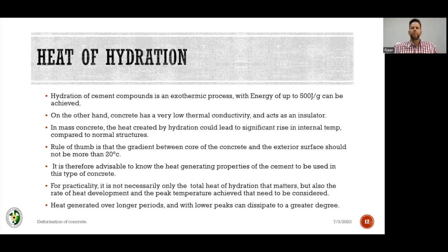consultant and the client. Yes, if you were to place that concrete while it's in its initial heat of hydration, you are now breaking the rules, because you are placing concrete that is warmer than 32 degrees. You are putting it into a shutter, into an opening, into an excavation, and that heat then gets trapped. It's like a cool bag. That 32 degrees will stay there.